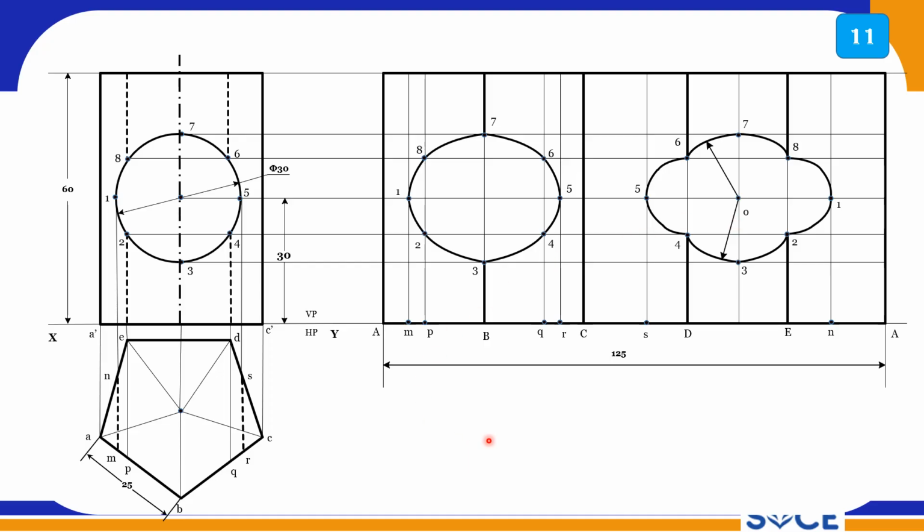The thick lines you have to draw carefully, and the B line, it is a hole. So C to this upper surface, and 3 to this B point should be drawn with thick lines, whereas D from here to here thick line, from 6 to the upper surface thick line. And this is your development when a through hole is drilled. So this is a very simple problem, but you have to do it very carefully. You have to draw the reference lines and reference points carefully. You have to measure them, and you have to mark them in the corresponding development.